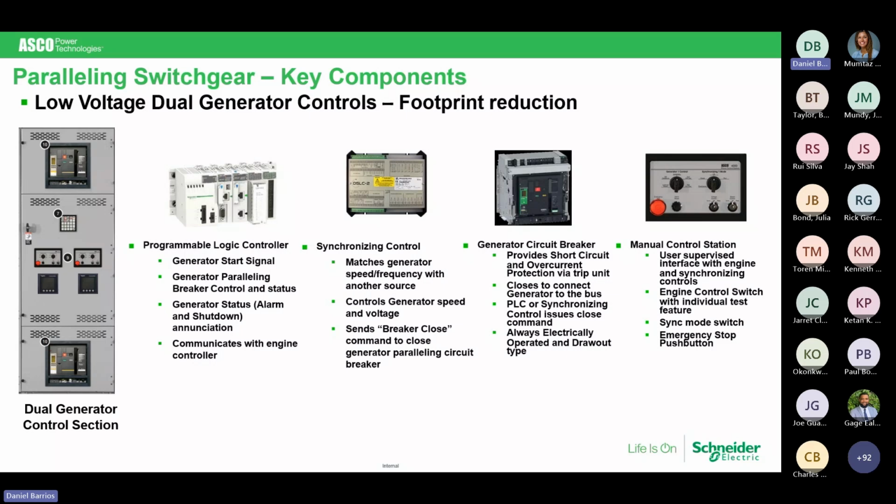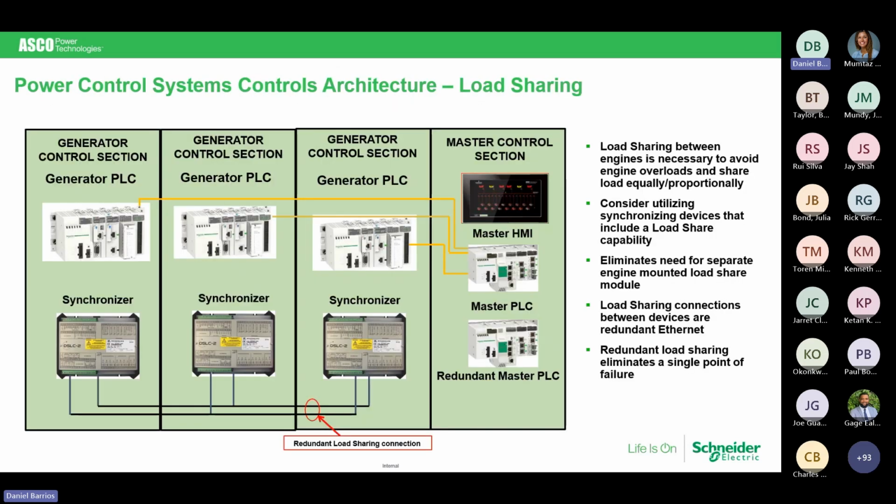The other thing you may want to consider is arc flash. If I'm operating the gear standing in front of it, even to the side, I'm within an arc flash area. For safety, you may want to carry that set of controls outside of the area, or at least to another area in the room or such. The programmable logic controller is in each one of our generator sections. Again, we do provide a synchronizer, breaker, and control switch, even in the dual generator control section.